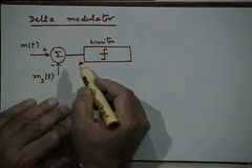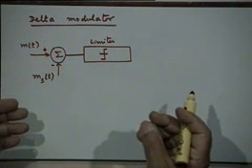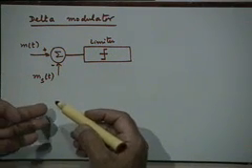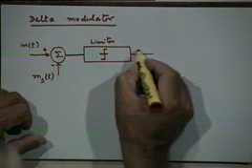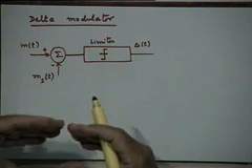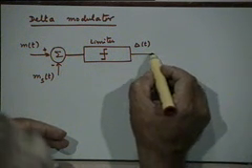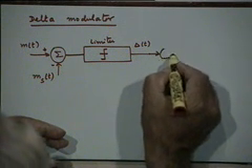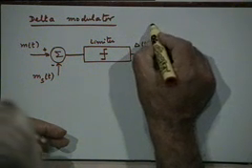So basically the difference output information is encoded into a binary form, right? You are only looking at the polarity of the difference, not the actual value of the difference. Is that clear? Whether the difference is positive or negative, whether m(t) is more than m_st(t) or m(t) is less than m_st(t), that's all you are looking at. This signal is a kind of quantized representation of the difference, a very crude quantization, where the quantization produces either a plus 1 or a minus 1, right? If the difference is positive, it produces a plus 1. If the difference is negative, it produces a minus 1, and I am representing this quantized difference signal as delta(t), right? This now, and this is where the modulation comes, modulates or multiplies a pulse train, and for the moment we will take this pulse train to be an impulse train for mathematical convenience, right? So here is a pulse generator.